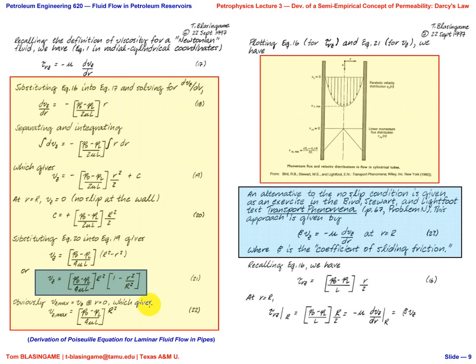So if you set little r equal to 0, that velocity is a maximum. From now on, anytime you're dealing with a laminar flow system, where is the maximum velocity? In the center line. And that's exactly what the graphic on the other side shows. They made this graphic vertical, but it would be the same if it were horizontal. So you're looking at a parabolic velocity distribution like this, and the point of interest that we're talking about right now is there, and it's defined by this.